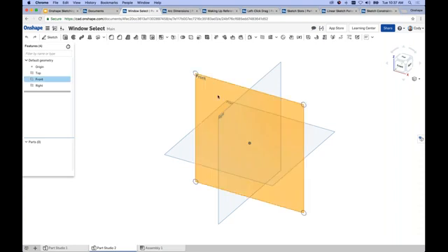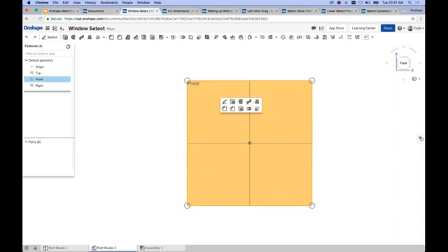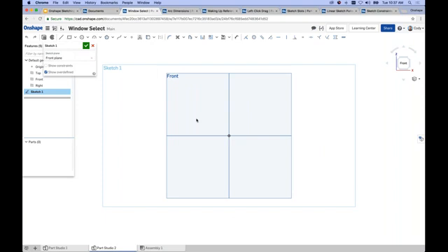And as I mentioned before, the key to this is as you're sketching, let's say for instance I'm sketching lines. As soon as I left click to place the geometry, you'll see a number, and there's a little box that appears around that number. So as soon as I place whatever sketch geometry I'm placing, that number appears. I can then go immediately to type in the value. In this case, we'll type 2.5, enter, and now I've not only sketched the line, but I've also added a dimension to constrain the line, right?